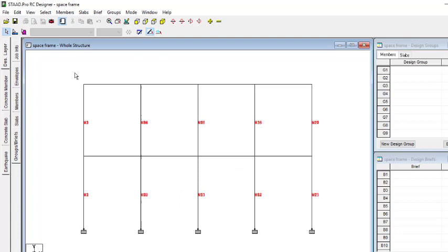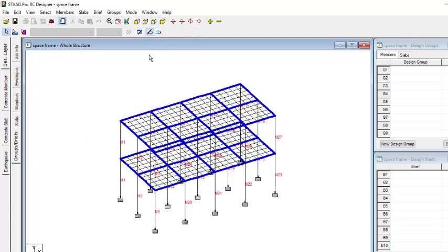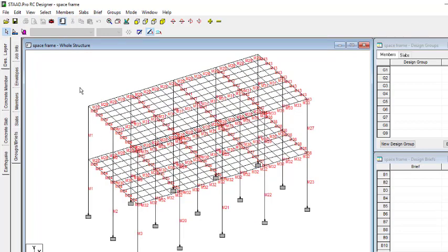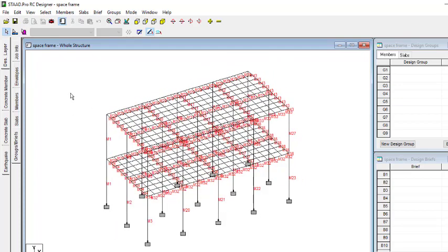Let's put it in front view and then select all of the beams, and then select this one with Alt Control. Let's put it back in this view, and then we're going to use the auto form member again. So it has formed all of that, which is very good. So we also need to form slab. We need to form the plates into slab.